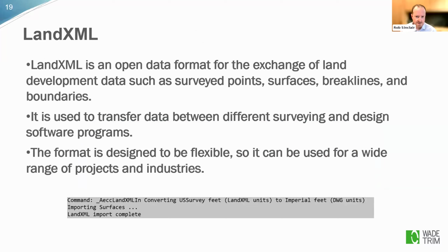A LandXML file, this is the ideal way to transfer data between design software. So, Civil 3D to Bentley products, you name it. LandXML is a universal file format that can be transferred between all these different programs. So definitely use that if you can.